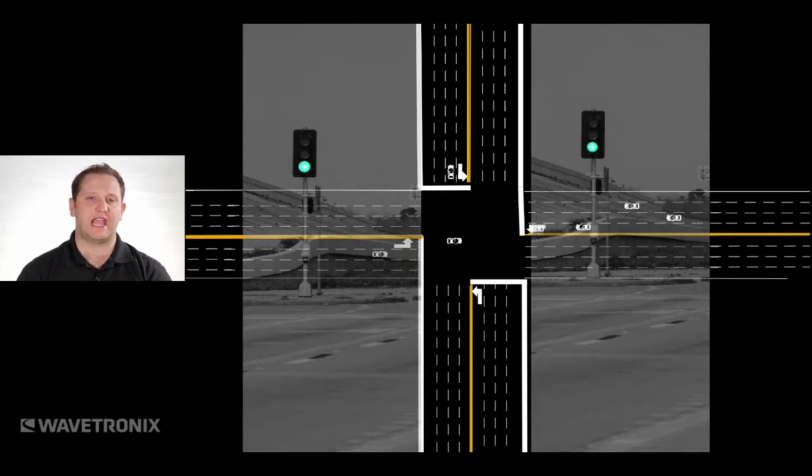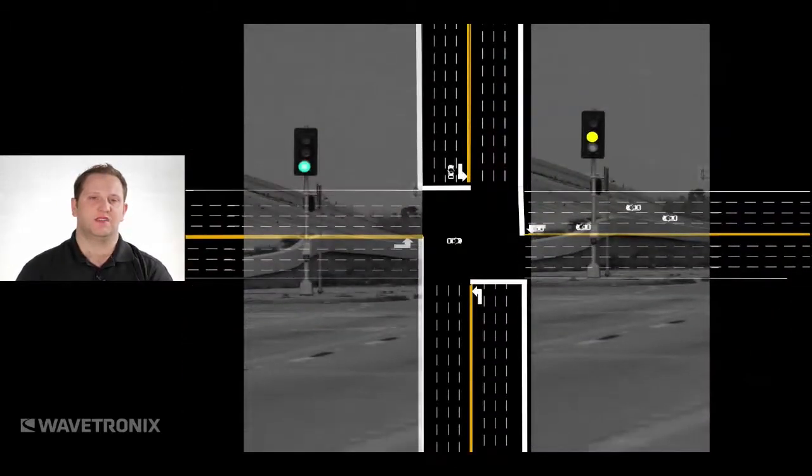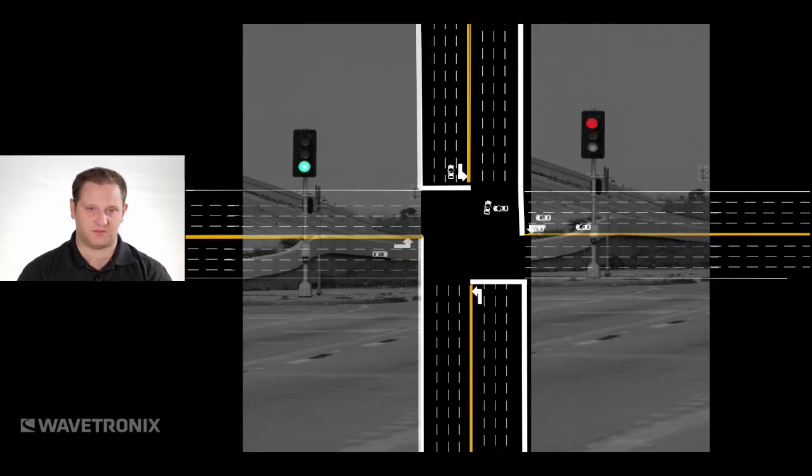And so what happens is the light turns yellow on the driver, and they assume that both sides have a yellow light, but they don't. And so that driver continues to proceed through the intersection, and then because this approach didn't have a left turn or a yellow light, they didn't stop, they run into the driver, and it causes an accident.